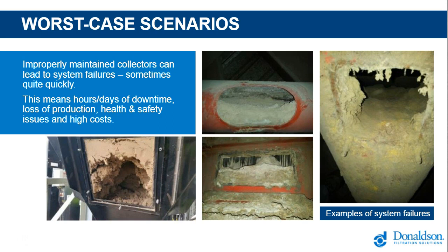But other things such as too low conveyor speed, too high delta P, all of that can result in, for instance, an extraction of only 2,000 cubic meters, whereas in essence, your system was designed or set up for extracting 6,000 cubic meters. As a result, you can have impacts on your health and safety, impacts on the environment, impacts even on your production. But even further, the accumulation of dust can lead to explosive situations.